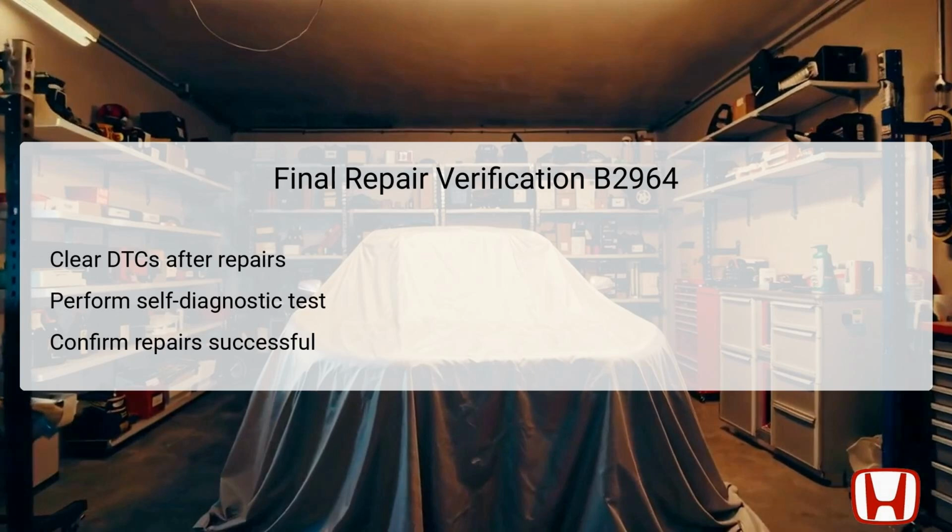Following this, perform a self-diagnostic test, either through the HDS or manually via the climate control unit. If the previous codes do not reappear, it confirms that the communication line is restored successfully. It's important to ensure that all systems function as expected, confirming that the vehicle's climate controls operate efficiently, thus completing the repair process effectively. Verification is crucial, ensuring long-term reliability of the repairs conducted on the climate control system.